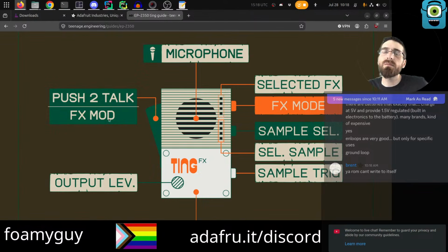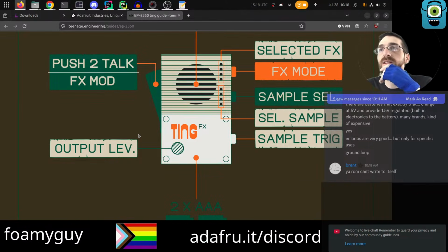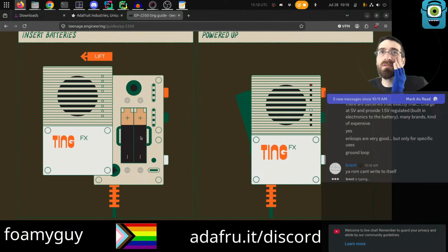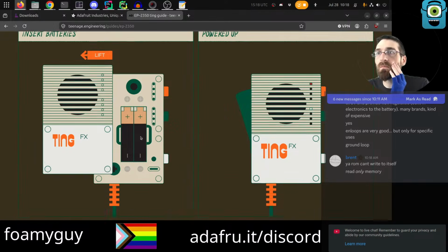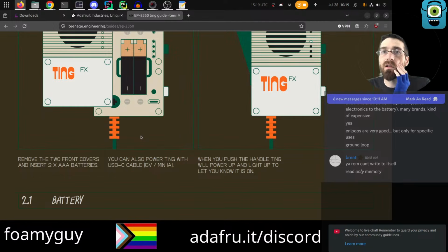Somehow it does. Well, I don't know if it's writing it or if it's part of the firmware or what. Could be part of the firmware, I guess. Somehow, though, when you flash back the stock firmware, it does put main.py and a README file back into there. The README file is not super useful because you can't access it except through the REPL, really, but it's read-only memory. I guess it's baked into the firmware then. That doesn't make sense though.